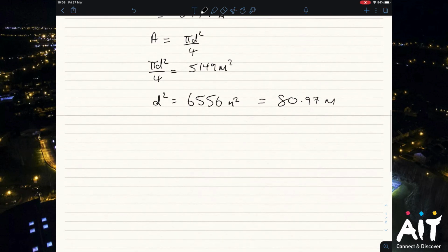It's key for us to remember that the power available in the wind is equal to a half times the density of the air times the area times the wind speed cubed. If we wanted to find any one of these components, we want to be able to manipulate that formula. The power at the rated wind speed is the coefficient of performance times half times the density of air times the area times the velocity cubed times the overall efficiency of our system.